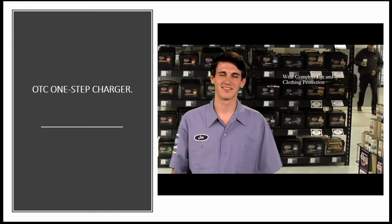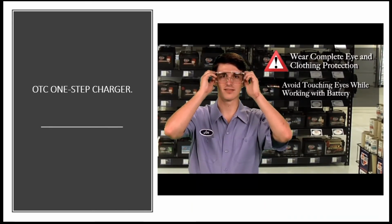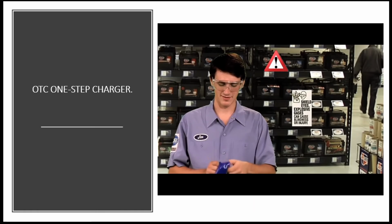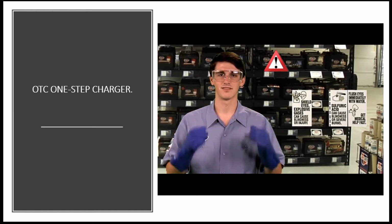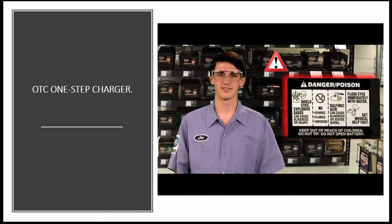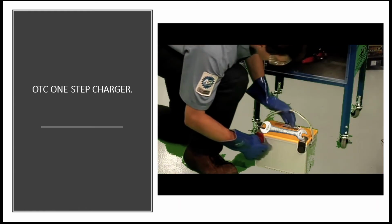Personal precautions. Wear complete eye protection and clothing protection. Avoid touching your eyes while working near the battery. If battery acid contacts skin or clothing, wash immediately with soap and water. If acid enters the eye, immediately flood the eye with running cold water for at least 10 minutes and seek medical attention immediately. Never smoke or allow a spark or flame in the vicinity of the battery. Be extra cautious to eliminate the risk of dropping a metal tool onto a battery. It might spark or short circuit and cause an explosion.